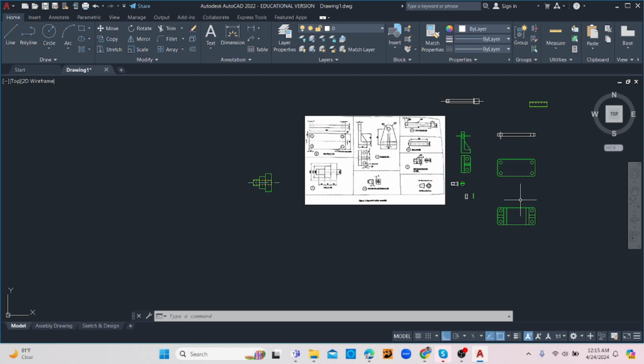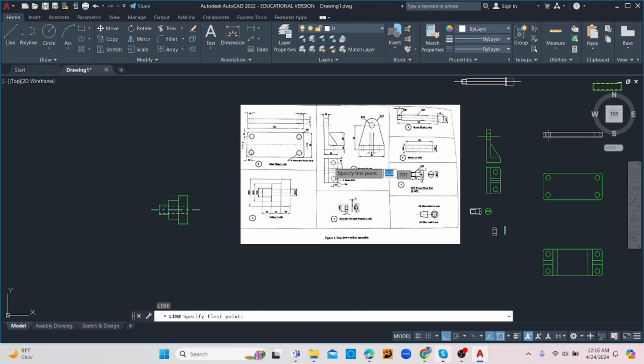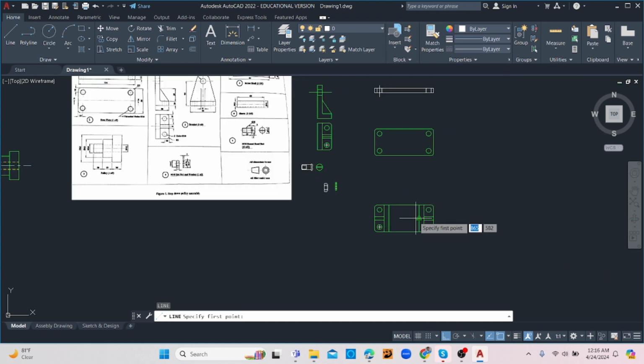The shaft. Alright, if you recall, there is a hole inside of the bracket right here, where the shaft will pass through. You can see that circle. We need to represent that as well on ours. We did not add it, so we have to add it now. Now the diameter of that is 12, so we're now going to easily add that 12 millimeters gap in here.